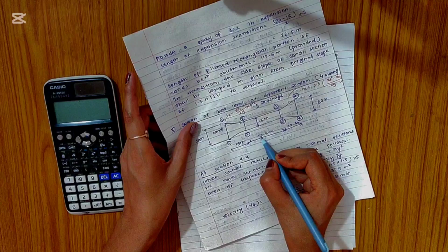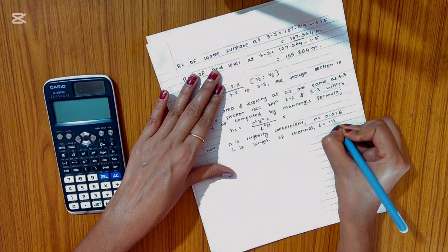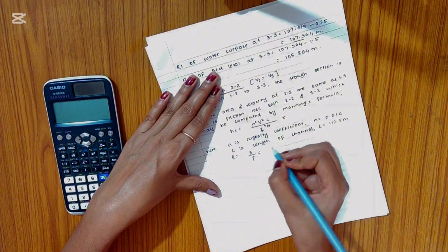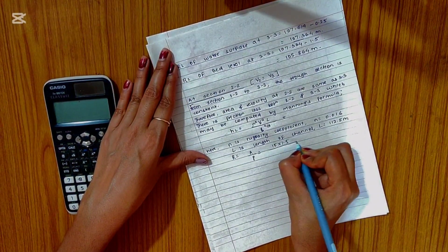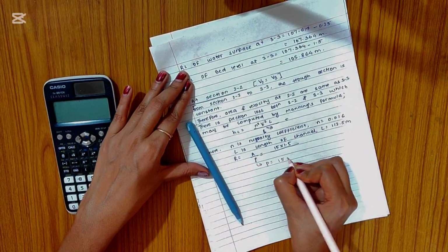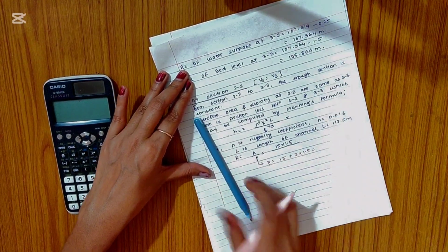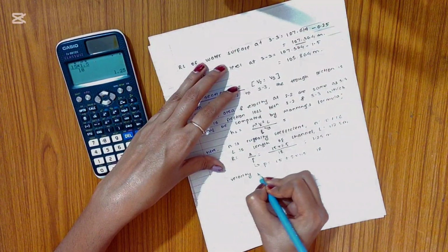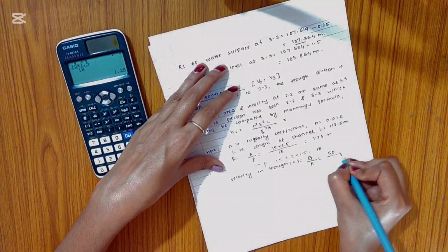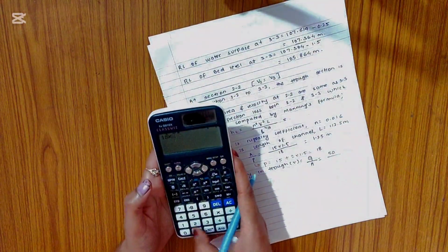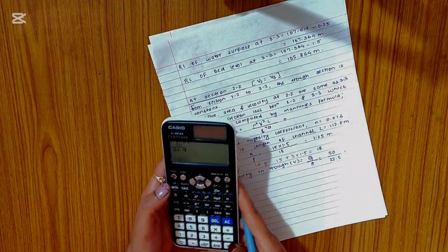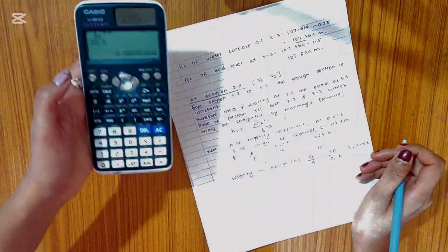So L is equal to 112.5 meters. Also, for the hydraulic depth, we have R is equal to area by perimeter, where A is equal to breadth into depth, which is 15 into 1.5, divided by the total perimeter. Here the perimeter is equal to breadth plus 2y, which is 2 into 1.5. Now the velocity in the trough section: V is equal to discharge by area, whereas discharge is 50 and area is 15 into 1.5, that is 22.5, which will be equal to 50 by 22.5, that is 2.22 meter per second.